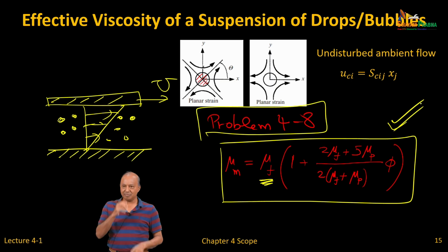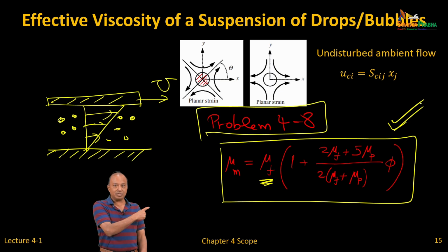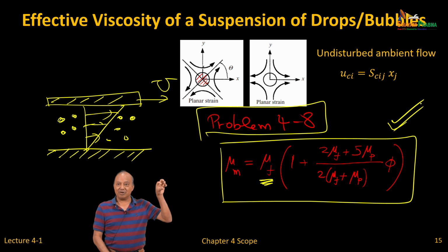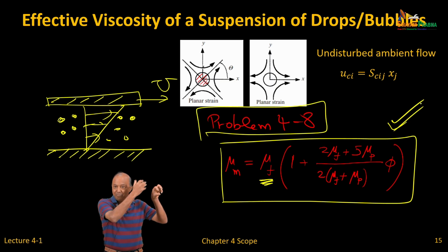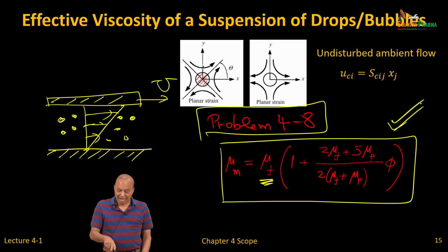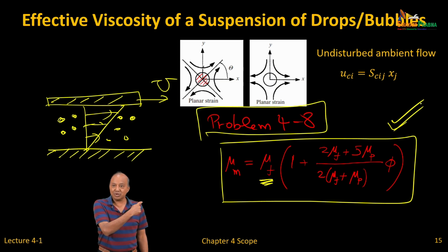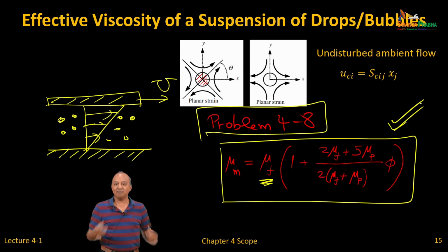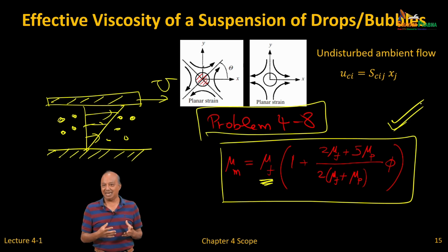If the gas bubble remains spherical, can you still use Einstein's relation for the correction of the viscosity? No, I would use this, not Einstein's. Einstein did it for the rigid particle, so his stresslet is for a no-slip boundary condition. In the problem you see here, the fluid outside is slipping and there is some fluid motion inside the droplet.